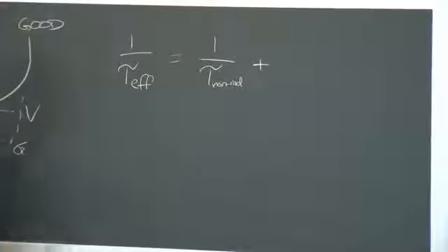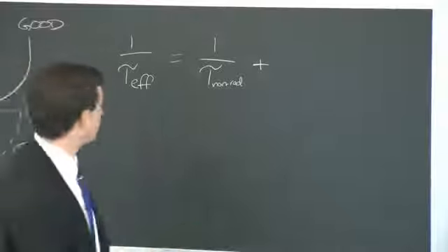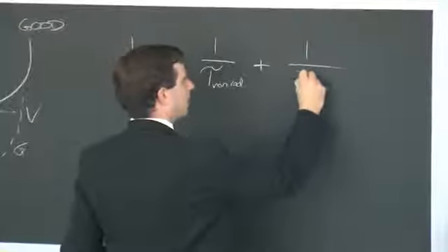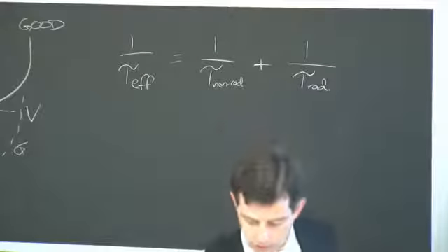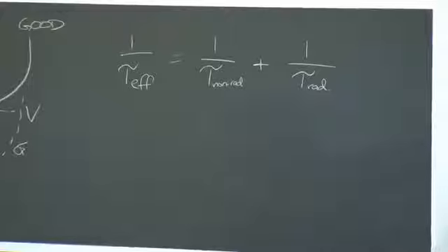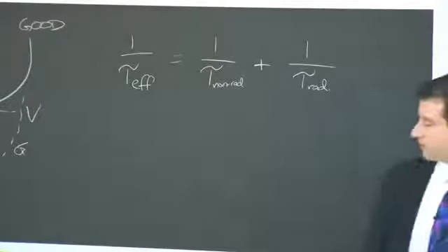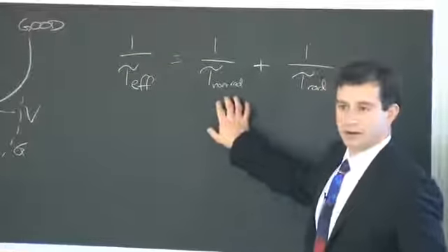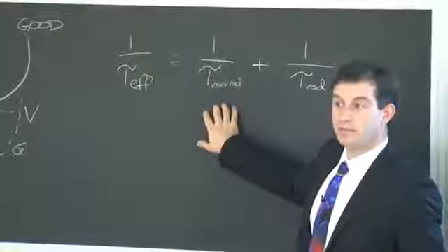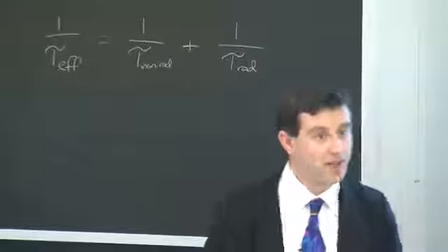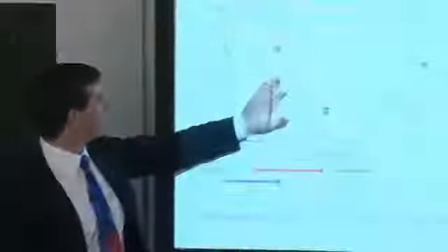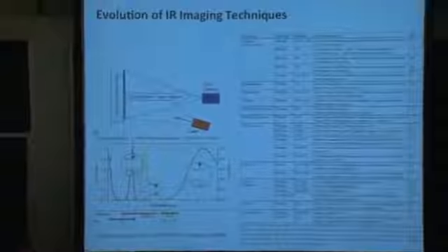This comprises Shockley-Read-Hall recombination, Auger recombination, a bunch of different recombination mechanisms. And then we have 1 over tau radiative, which is essentially this recombination mechanism shown right here, which is just the band-to-band recombination. So if you have defects around, that will lower the lifetime, the non-radiative lifetime. If you have tons and tons of defects, the carriers will most likely recombine through the defects and not through the band-to-band. They will only recombine with band-to-band if there is no other recombination path left available to them, right? It's a question of probability.